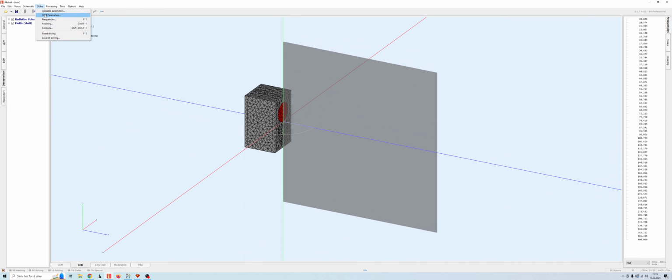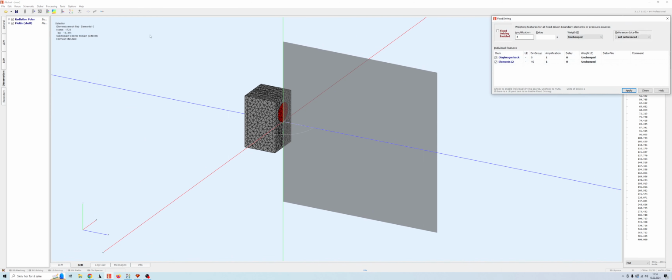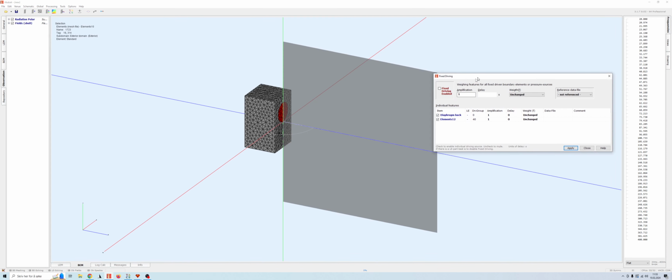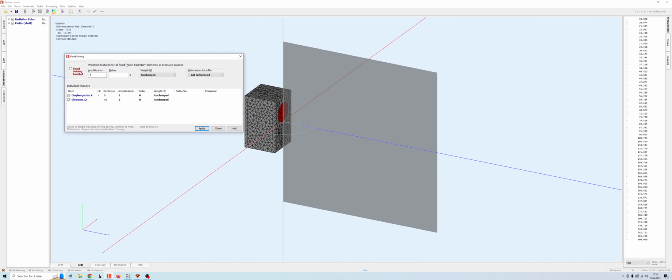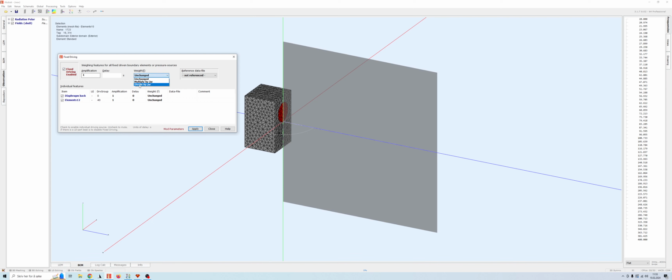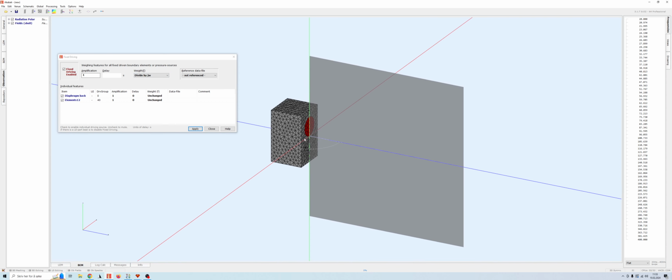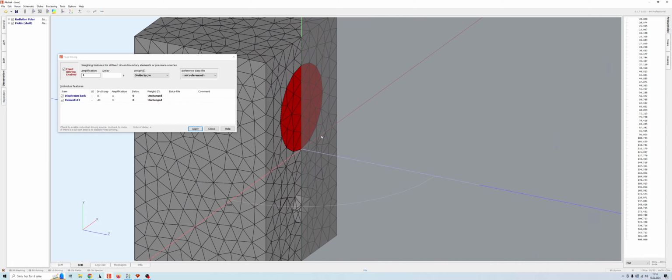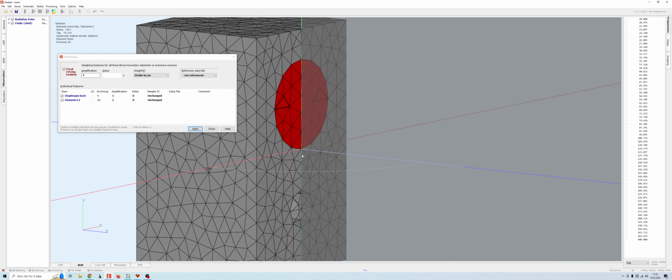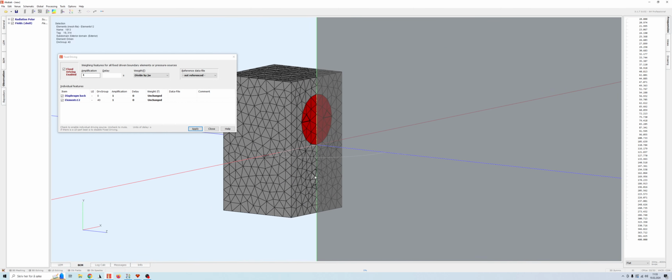So we don't need to do that, but we do have to set fixed driving in this case, since we have not made a lumped element model yet. And here we have to make sure a fixed driving is enabled, and we'll just choose constant acceleration again. So we click apply, but there is one trap you can fall into here, and that is both of these drivers, the inside and the outside, both of these are moving in their normal direction.